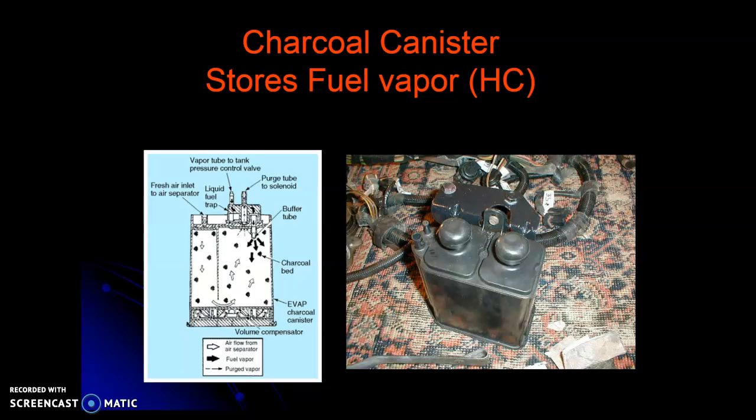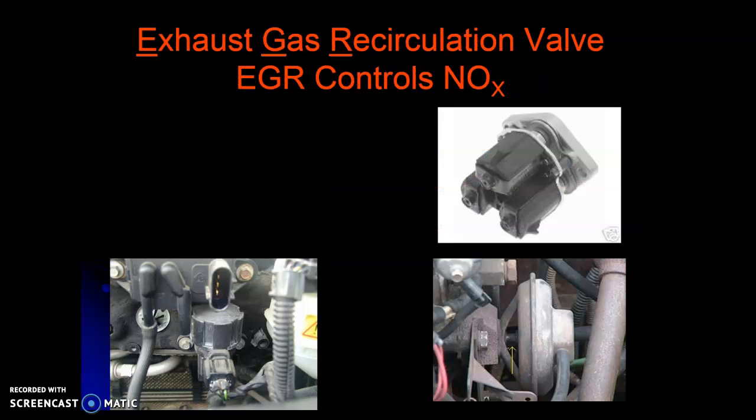Again, if you're going to fill up your gas tank, kind of an old tech tip: when it clicks and turns off, don't keep clicking it, because you can get some raw fuel into the charcoal canister and you don't want it to get ruined. It's not meant to have liquid fuel, just vapors. So again, when it clicks off of the pump, you're good. One click and you're done.